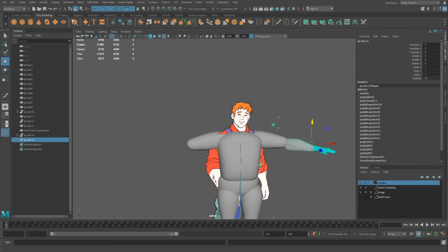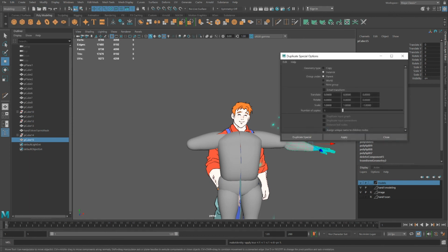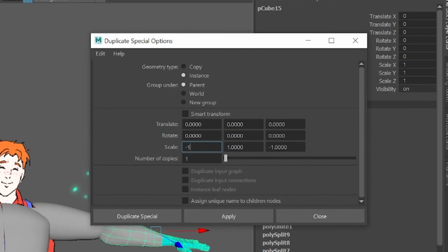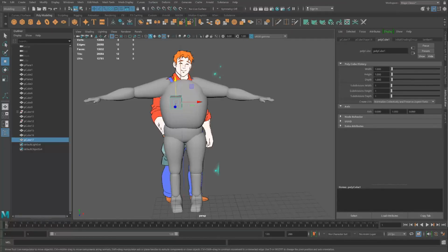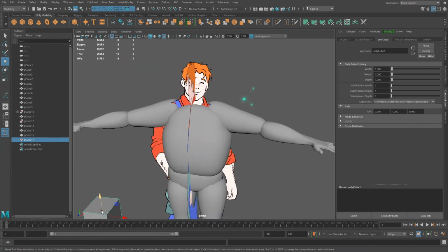Have this hand selected. Click on Freeze, Edit Duplicate Special, Panels box. It could be flipping across the x-axis, so -1 for x. I previously flipped across the z-axis. Let me put 1 in there. Let's finish this off with creating the neck and also the head.